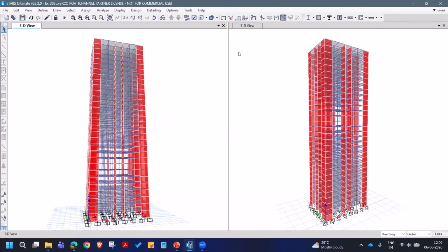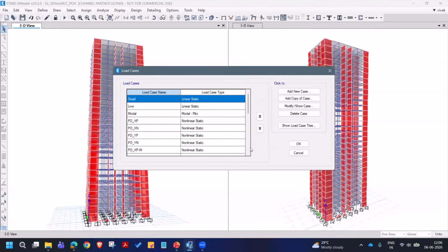From the linear analysis, we will not have much information regarding this, so we'll have to perform a nonlinear analysis considering the material nonlinearity. Instead of a nonlinear time history analysis, which will be computationally heavy, I used a pushover analysis for this.